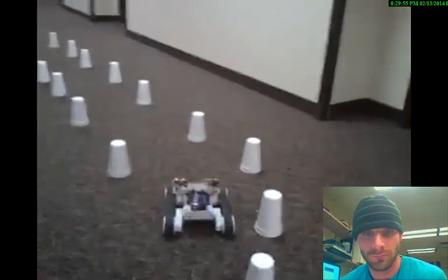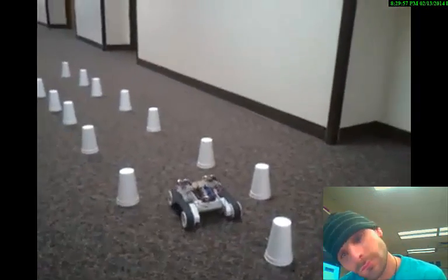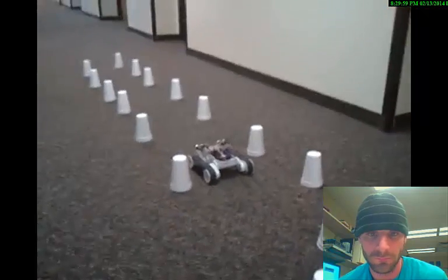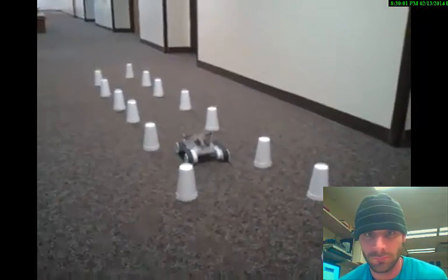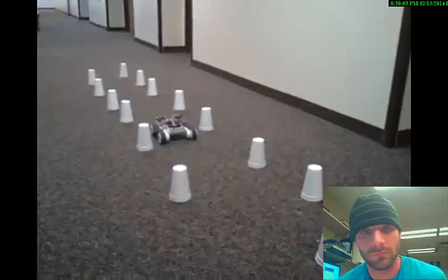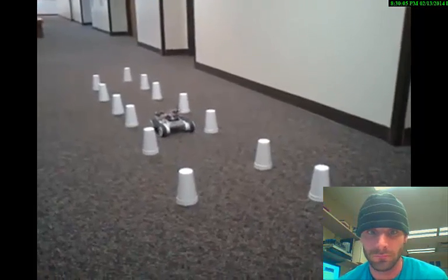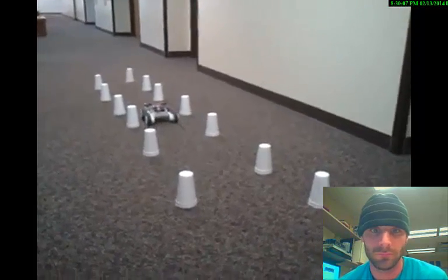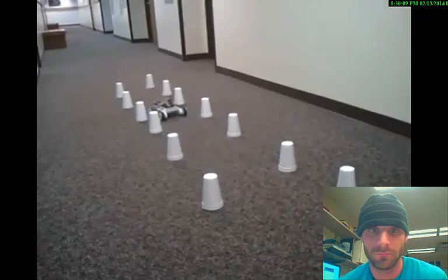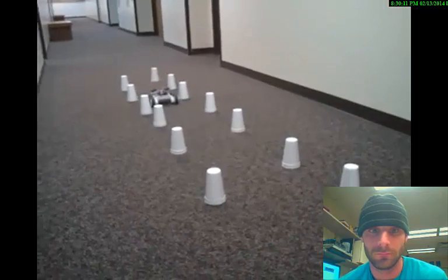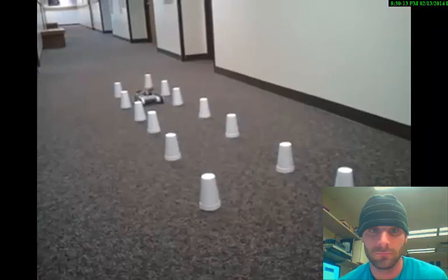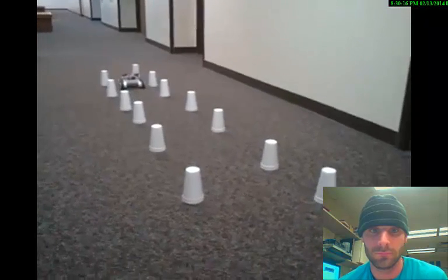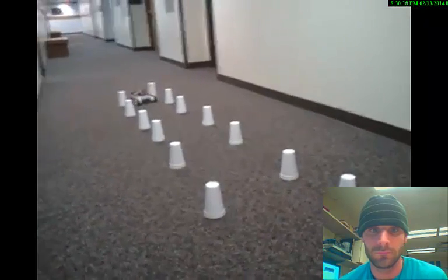Those infrared sensors are going to be for close proximity like that. So whenever he's in close proximity, one cool thing with light is it doesn't just bounce in one direction. It doesn't hit and then go off in a direction. It actually hits and spreads out and goes everywhere. So with an infrared sensor, it doesn't matter what your angle of approach is, you're always going to get some infrared back as long as you're in a certain tolerance. And I'm going to set his tolerance to about 10 centimeters, 15 centimeters.